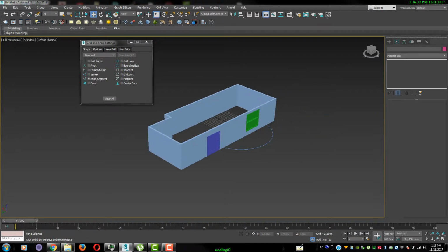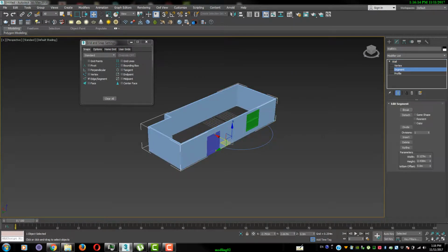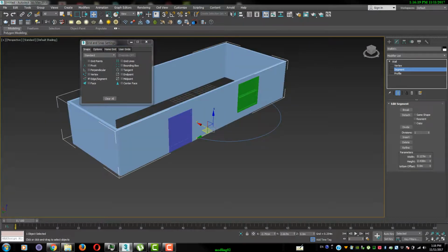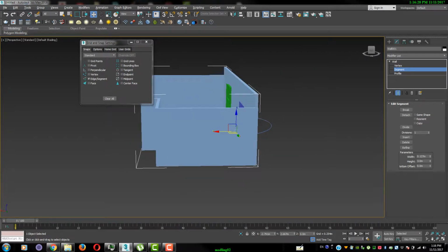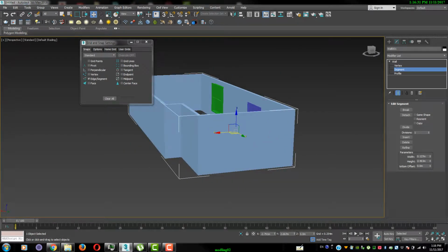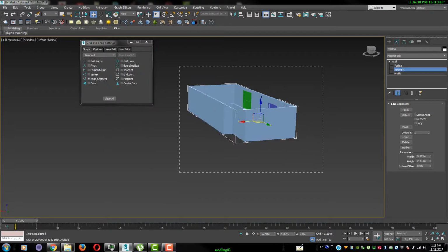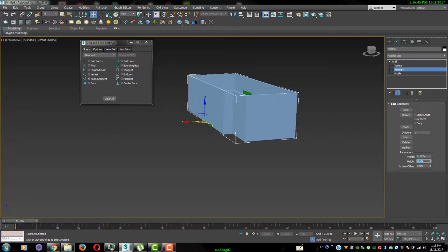Okay, so I go back here, select the segment. The height is 2 meters. I can change it to 3 meters. You can control this for one segment or one profile. We can choose the profile. So this is our segment. I choose all segments, and I give them maybe 3.5 meters height.